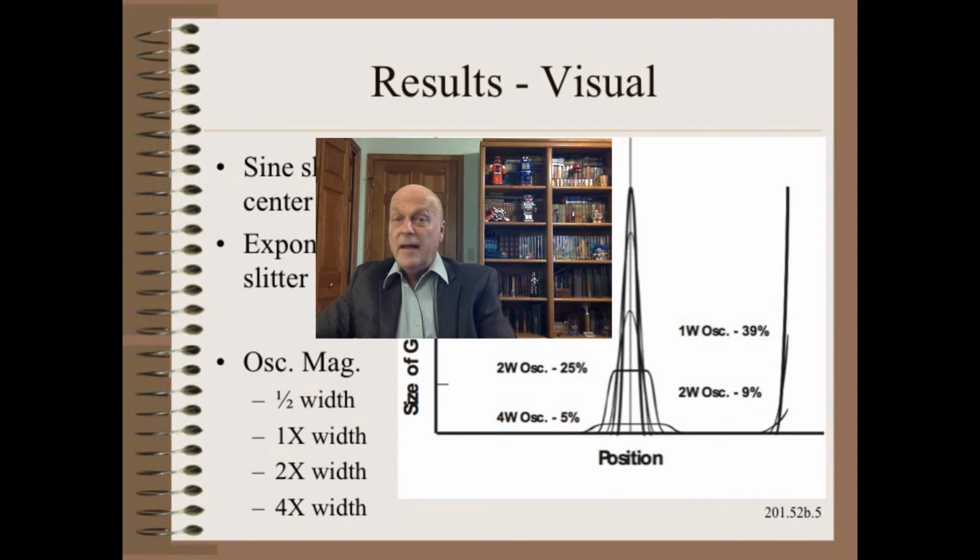The raised edge, such as perhaps due to slitting, has similar trends. The maximum defect intensity is decreased while the overall width is increased. Perhaps what might be surprising is just how effective oscillation is for raised edges. First, the defect tends to be much narrower to begin with. Second, the same relative stroke is somewhat more effective.